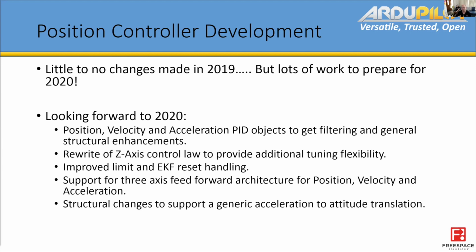So looking forward to 2020, there's been a lot of work being done in the background as we do this S-curve stuff to update the position, velocity, acceleration PID objects in the position controller, and take a lot of the stuff we've learned in the attitude controller as that's evolved, making those objects consistent with the attitude controller, but also restructuring things to be cleaner, based on what we've learned in those PID objects.